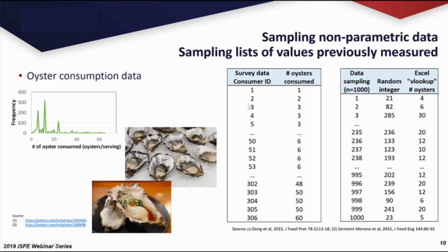So again, this is the data. We want to have a final 0.65. These are the 3 ingredients. We fixed this to be at 0.4. For simplicity, we're saying the raisin and the pineapple will have the same water activity. And the fill weight would be 70 grams of almond, 50 grams of raisin, and 50 grams of pineapple. So when we do this calculation using the formula I showed you before, you'll find that this initial water activity value that we're looking for should be 0.75. But this is the deterministic calculation, and we're ignoring variability.